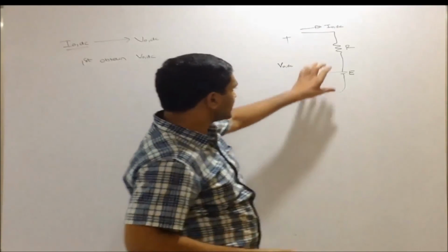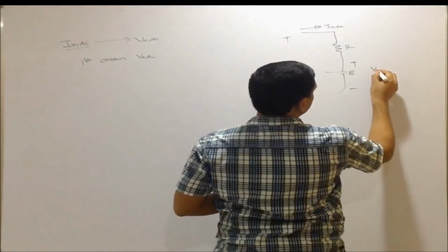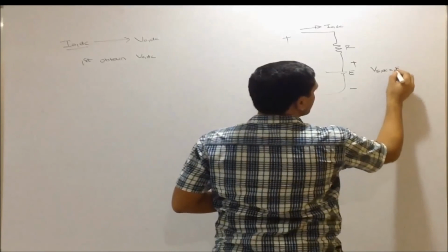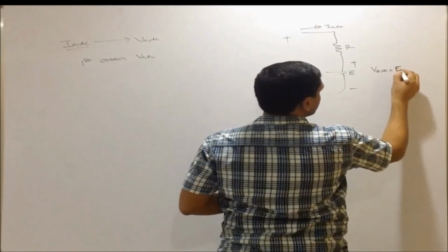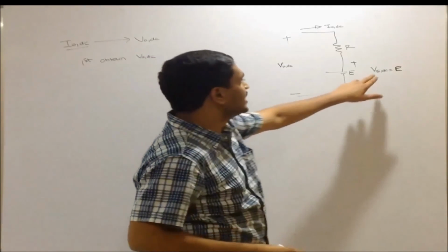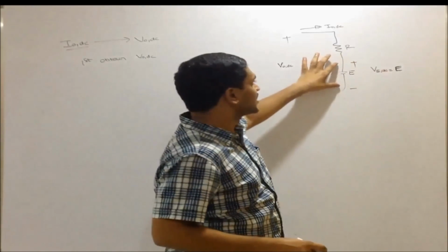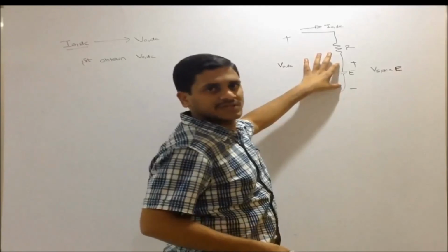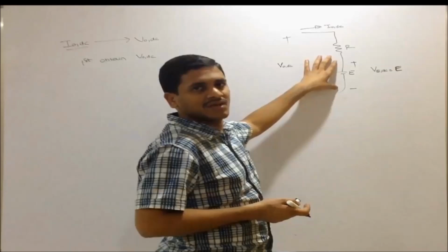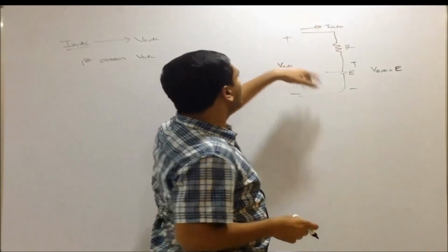You tell me what is the DC voltage here? The DC voltage across E is E, that is DC source. The average voltage across it is E. It is very simple, because it always maintains E. So peak value, instantaneous value, RMS value, average value, whatever you take, it is E. So I write the KVL in this equation.